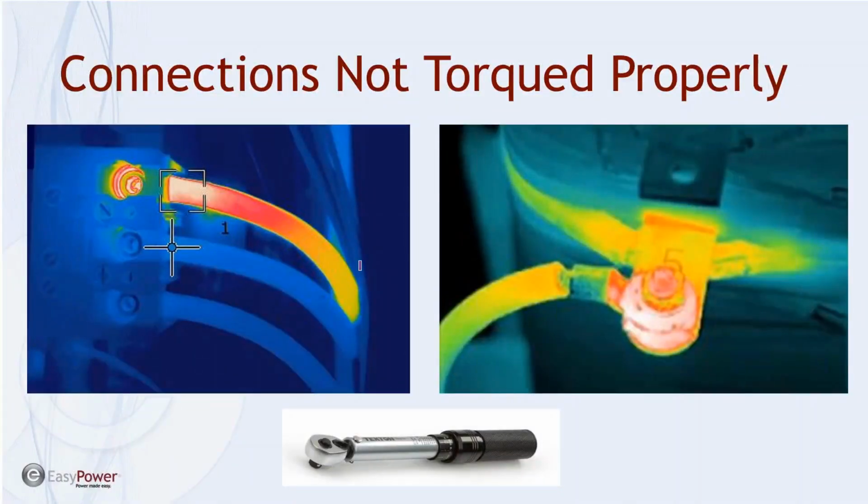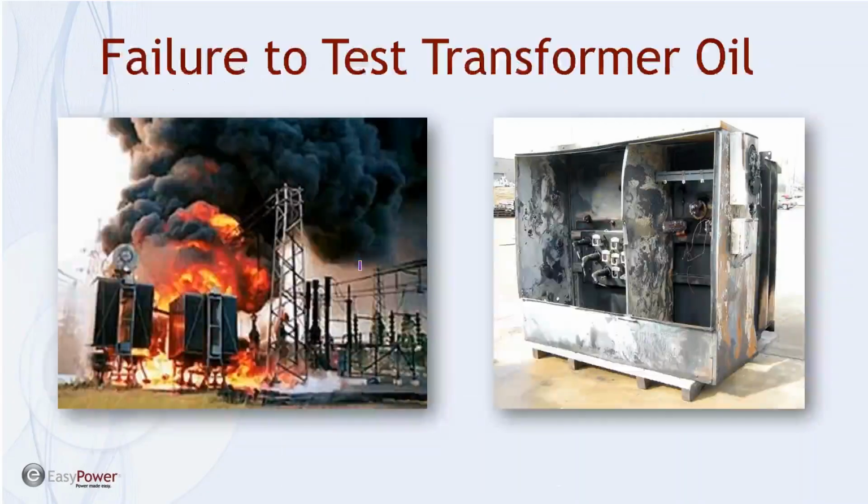This is the torquing issue. So when you have bad connections, that's the kind of heat that you may have built up from that. And by the way, infrared testing is a good thing to do as part of a maintenance program.